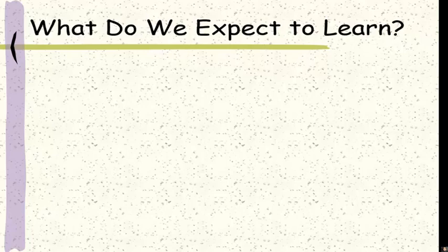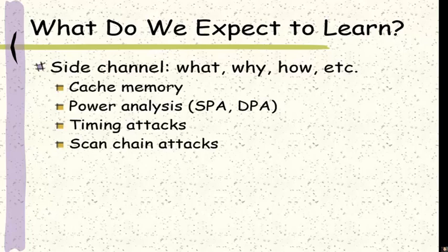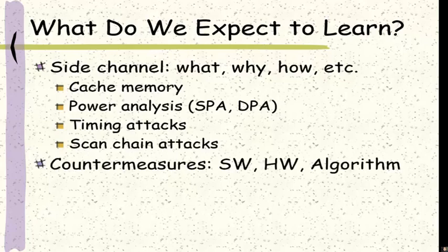We will discuss in detail four representative attacks: cache attacks, power analysis, including both simple power analysis and differential power analysis, timing attacks, and scan chain attacks. Of course, we will also talk about the countermeasures from software, hardware, and algorithms.